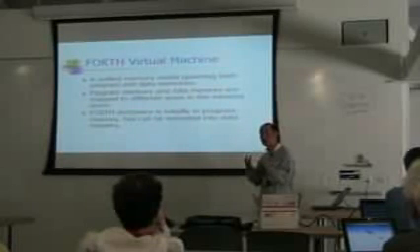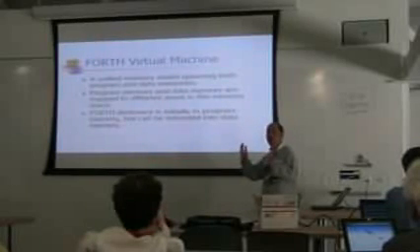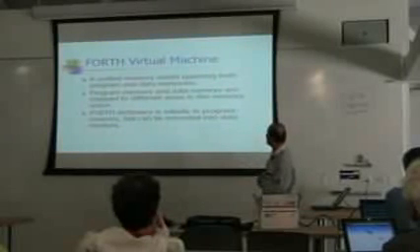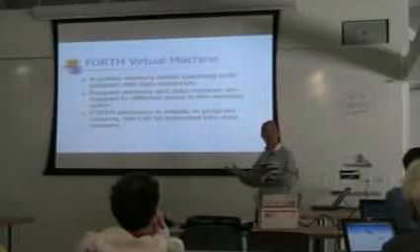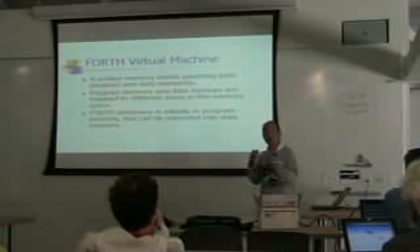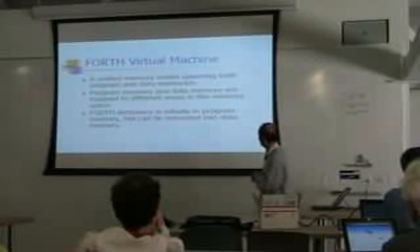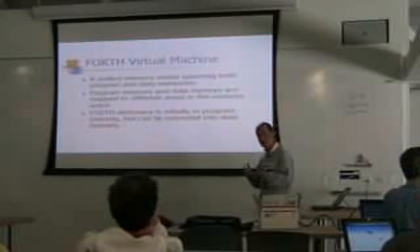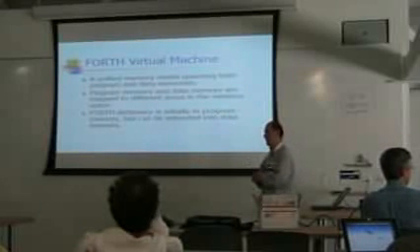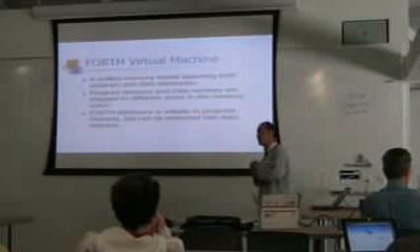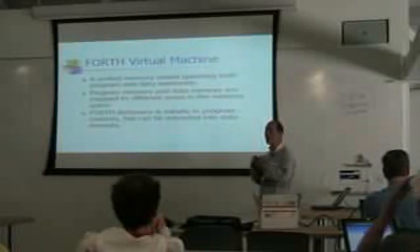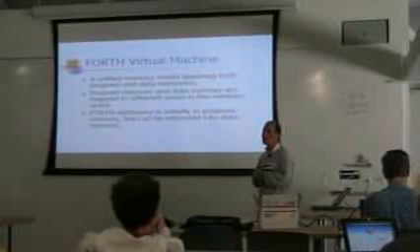This model will span both the flash memory space and the RAM space using the same instructions: fetch, store, cfetch and cstore. These pseudo instructions are smart in that they can determine whether you are fetching or storing from RAM memory, or fetching from flash memory.